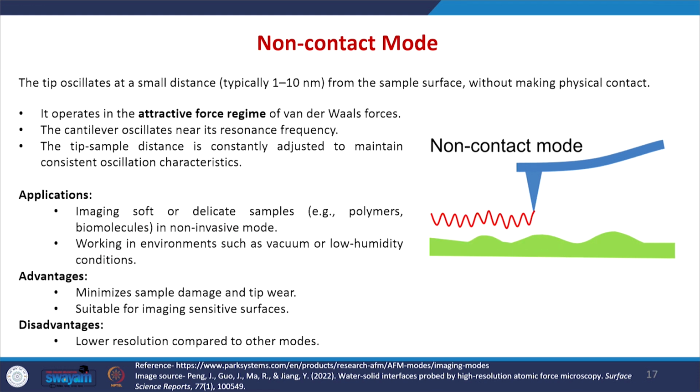Let us see the non-contact mode in detail. In non-contact mode, the tip oscillates at a small distance, typically between 1 to 10 nanometers from the sample surface, without making physical contact. You can see here the tip is not touching the sample, it is above the sample. It operates in the attractive force regime of the van der Waals forces. The cantilever oscillates near its resonance frequency. The tip-sample distance is constantly adjusted to maintain consistent oscillation.